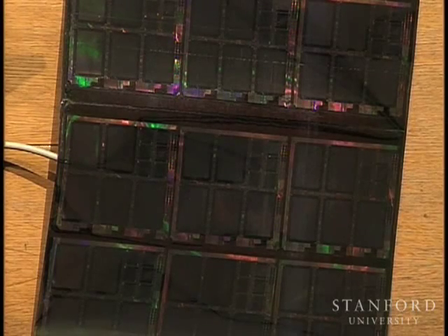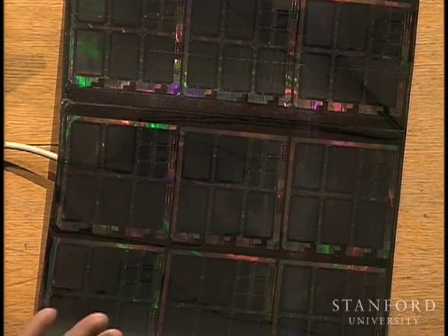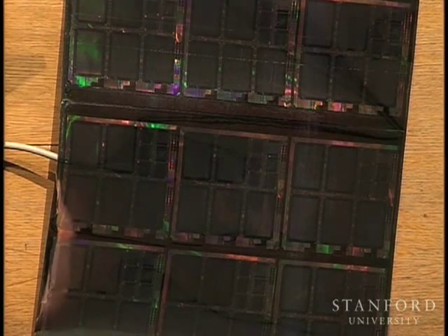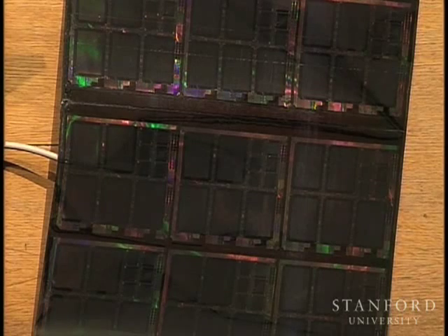So this process, which we call SAIL, is really key because it actually solves the hardest thing about plastic, that it's dimensionally unstable. It's not flat to start with, and you do anything, you look at it cross-eyed, and it'll change its shape by hundreds of parts per million. And if you're trying to align micron scale features over meter distances, 100 parts per million, that's a non-starter. You're just not going to be able to do it.